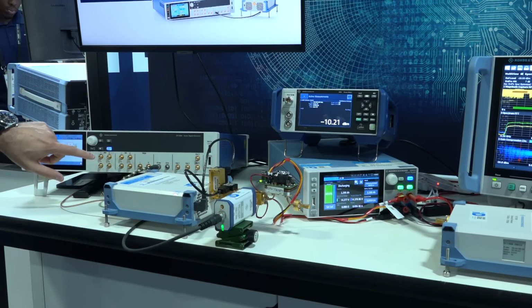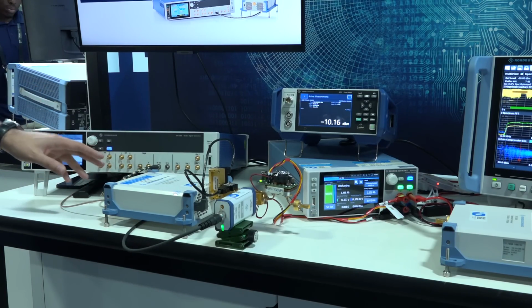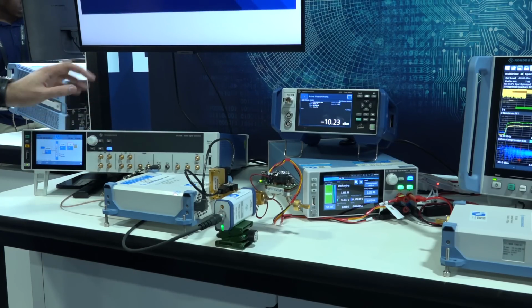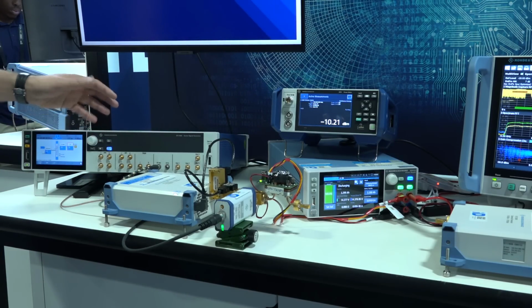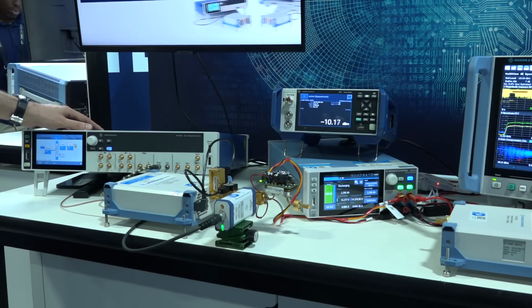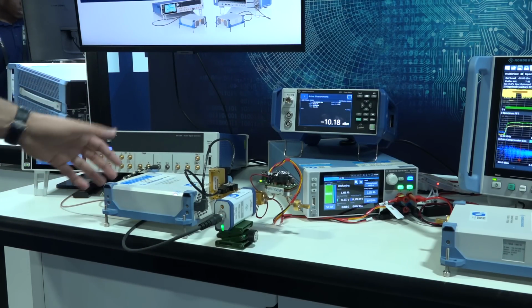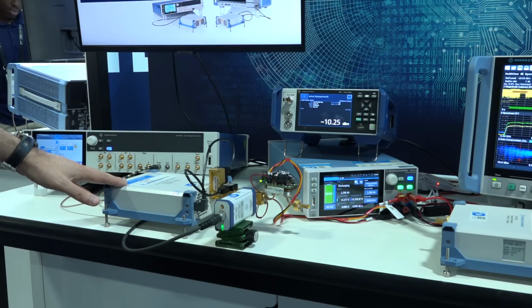At the same time, we do have the DAC outputs, differential, and each of those is 5 gigahertz, and differential mode is 2.5 gigahertz. So you could use it as a standalone IQ as well if you have your own upconverter or you just want to use the direct DAC outputs. So in one setup, we are not only measuring and providing extremely high bandwidth modulation, but we're also measuring precise power at the same time in one setup.